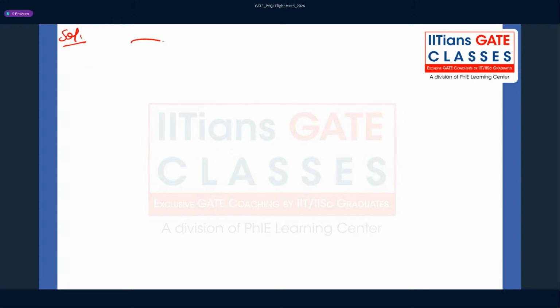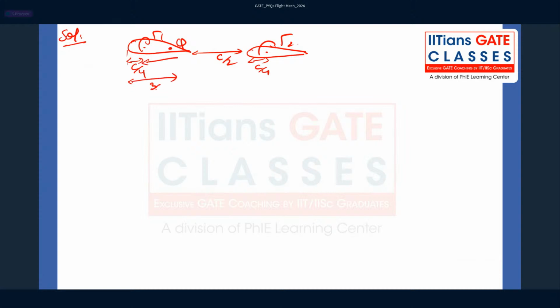So I have this airfoil like this. He says there is another identical airfoil, which is kept at a distance of c by 2 from the trailing edge of the first airfoil. So there are two circulations in here, capital gamma 1 and capital gamma 2. These are kept at a distance of c by 4, this also kept at a distance c by 4. And here my normal velocity is 0, right? So which means, because this is 3c by 4, this distance has to be c by 2, correct?